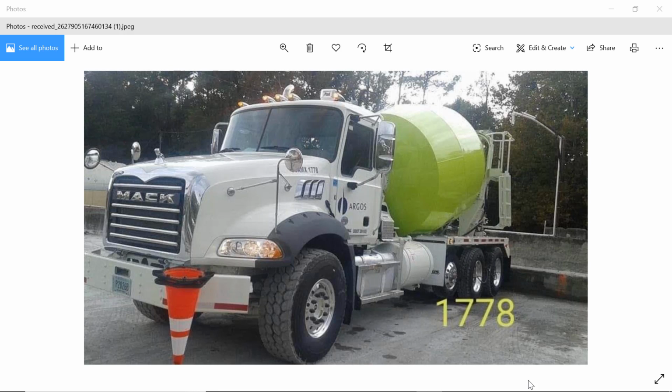Adjustment to the batch water is equal to 56.7000 plus 39.6140, which is equal to 96.3140 pounds. Adjusted aggregate and water quantities are: coarse aggregate 1,620 plus 56.7000 is equal to 1,676.70, which is equal to 1,677 pounds.